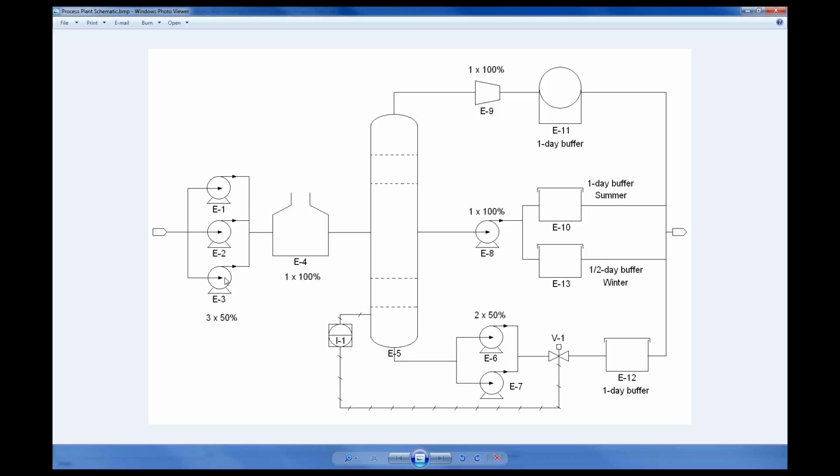What that means is that one of these pumps can be a standby pump. We don't need to operate it constantly. We can operate off just 2 pumps, and let the third be in standby until it's needed, until one of the first 2 fails. Now that introduces a tricky modeling scenario, what we call a strong dependency, where we have a standby arrangement.